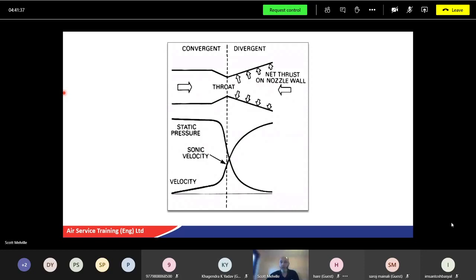If we then add on a convergent-divergent nozzle, we could turn that around and it could be a rocket as such. If more thrust is needed, it can be made from the exhaust pressure by fitting a convergent-divergent nozzle. The air leaving the shock wave is choked. The nozzle does not lose all of its pressure energy instantly. The pressure made in the gas is wasted and is dispersed. If we fit a divergent nozzle on the convergent nozzle, that will convert the last pressure into useful thrust.